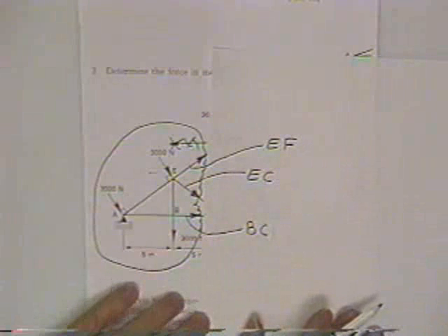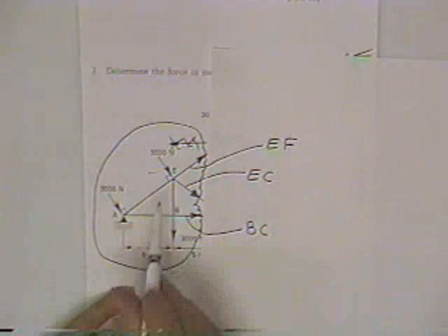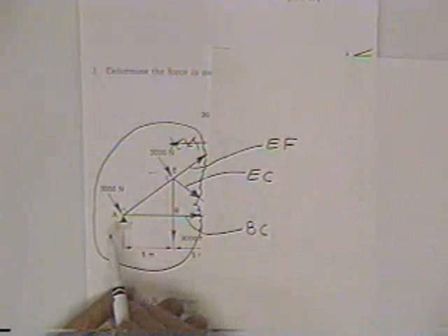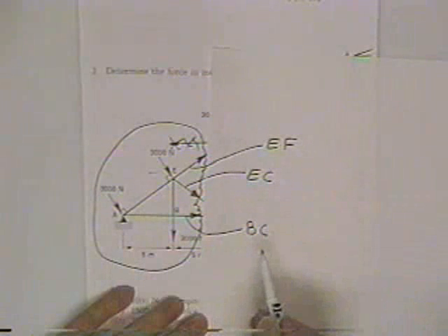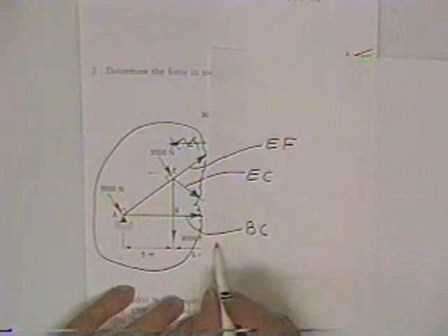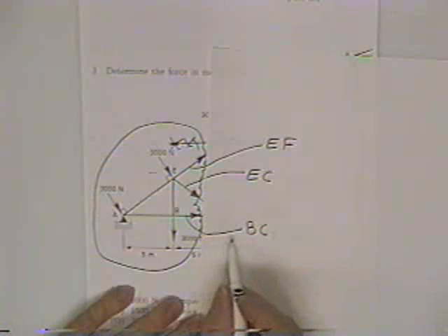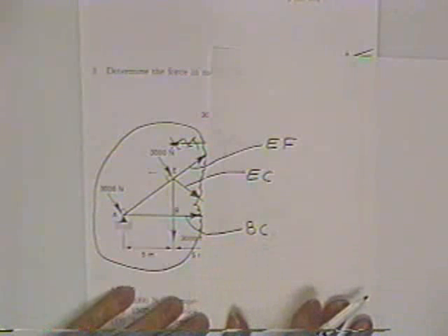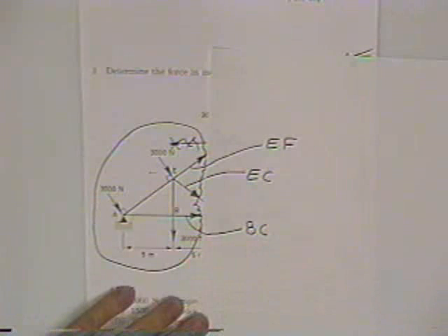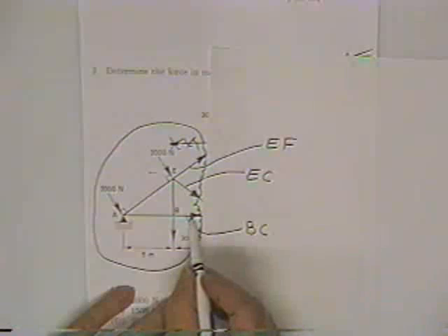Now then, it will be your job to put this little piece of steel in equilibrium by using the equations. Sum moments about any point, sum forces X, sum forces Y, all equals 0. Now here's the easy way to do that. There are 3 unknowns hanging out of that free body. It obviously is not going to just give up easy. You're going to have to do some work.